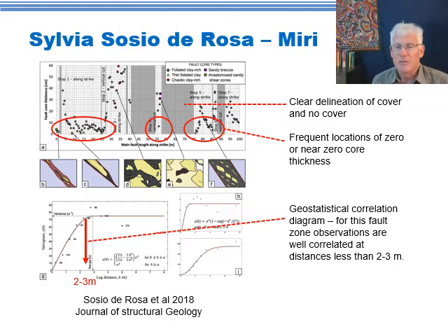So if you go more than 2 to 3 meters along the fault zone, what you saw earlier probably doesn't apply, and the conditions may be different. You may have a different type and style of fault rock. You may have different thicknesses. You may go from a thickness of 10 to 20 centimeters down to a thickness of 0.